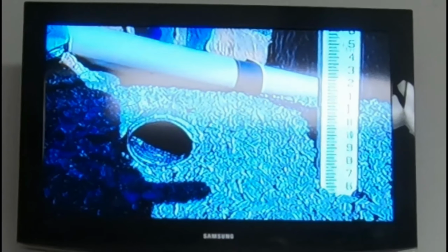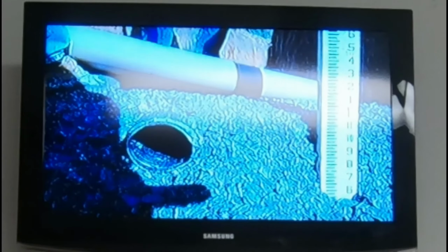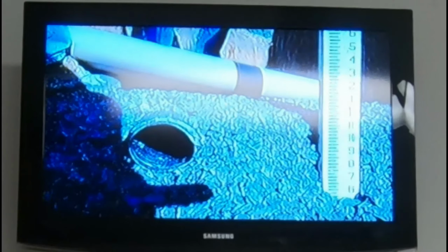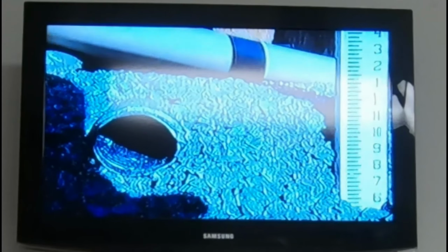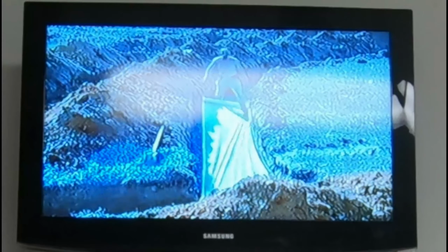The minimum depth of aggregate shall be 12 inches with 6 inches below the perforated pipe and filled to 2 inches above the pipe. Perforated pipe shall be laid in the center of the trench with the perforations oriented toward the bottom of the trench. A layer of pervious building paper, straw, or similar permeable material approved by the department's technical review committee shall be placed over the aggregate before backfilling.